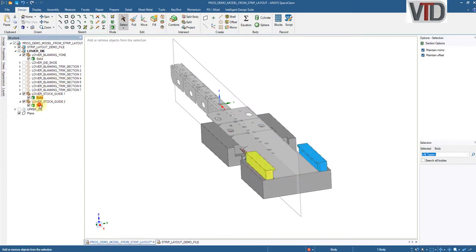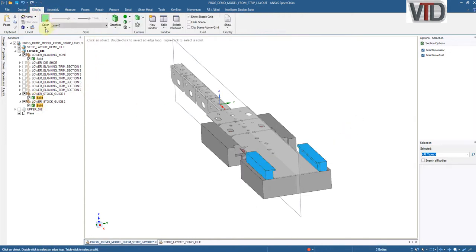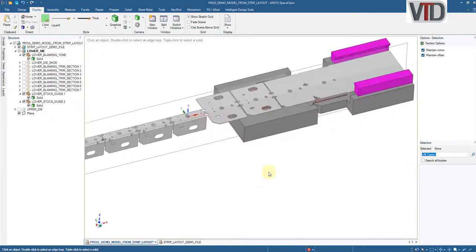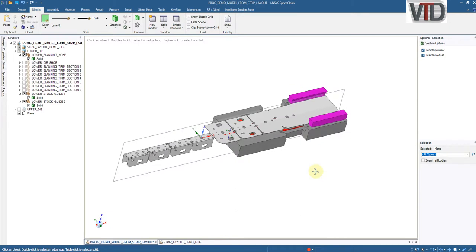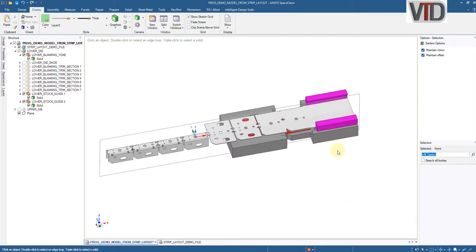Now we can pick the solids here, or we could triple click the solids on the screen. There's a few different ways we could pick them, but we want them to be the correct color for the material. As you notice, as I'm modeling this, I'm classifying every component by color as I go.